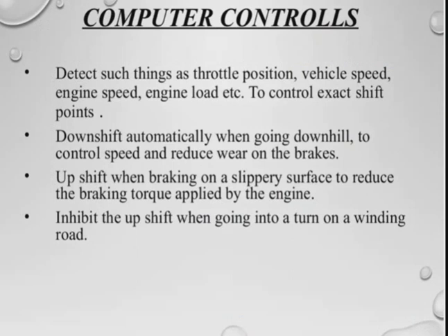So for that, it downshifts automatically when going downhill, to control the speed and reduce the wear of the brakes. Okay, and also it upshifts when braking on slippery surfaces, to reduce the braking torque applied by the engine actually.